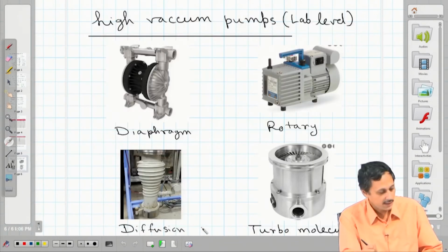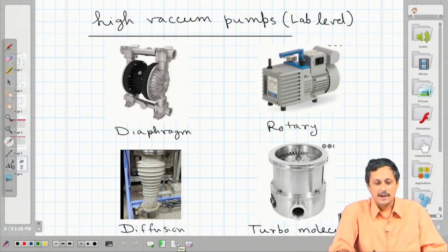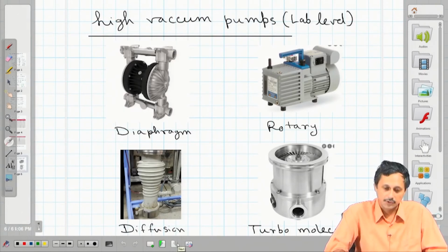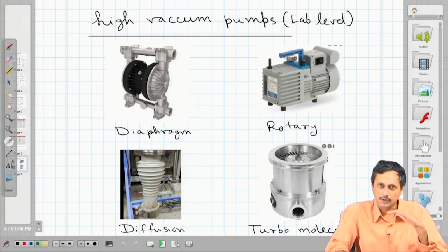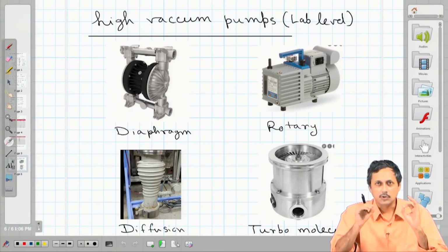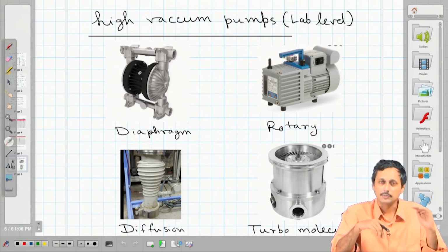Now, for the last part, we already have talked about low pressure, and as I have said, low pressure is essential for increasing the mean free path in a gas assembly. It has many applications. For example, in vacuum deposition systems, we always use low pressure in order to increase the mean free path, so that we have an even dispersion of molecules on a given surface. Ultra high vacuum systems like molecular beam epitaxy also exploit the same fact, so that epitaxial growth, layer by layer molecular growth, up to one or a few monolayers is possible on a selected substrate.